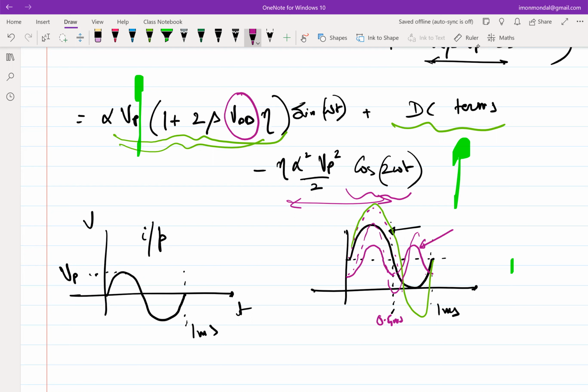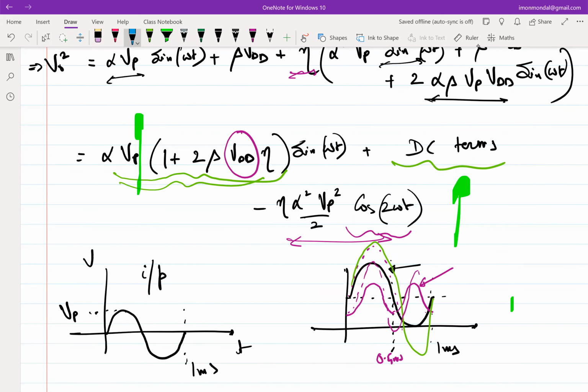Can you please explain the scaling of distortion? Okay, so why don't you tell me? Let's assume that the input VP has gone up by a factor of 2. So what do you see at the output? You get this linear term that goes by a factor of 2. This is the undesired term. This goes by a factor of 1.